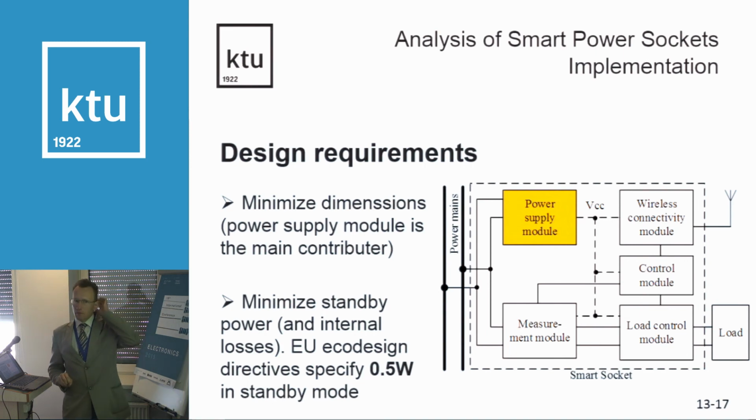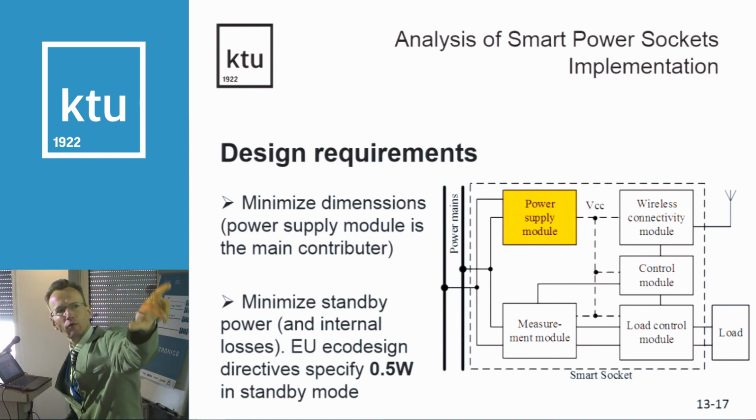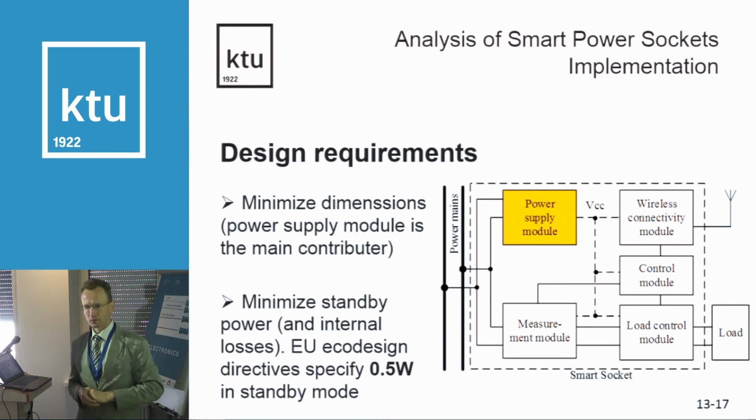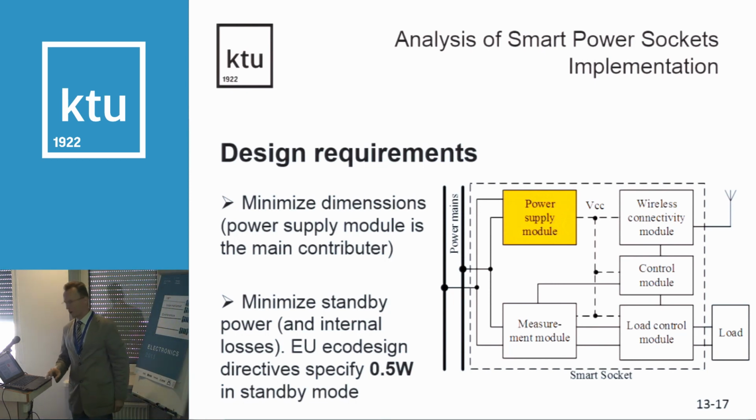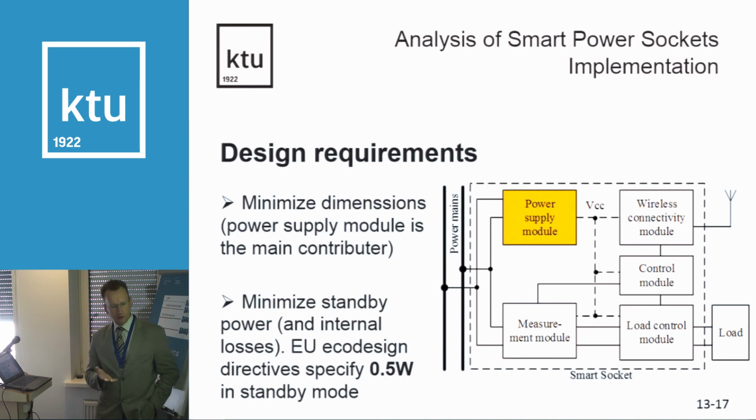Then I will finalize with the measurement errors. Several slides about the power supply module, which is responsible for the energy efficiency of the power socket itself. We were keen to find out if, using many off-the-shelf components, we can at least achieve the EU eco-design directives, which ask for less than 0.45 watts in standby mode of any consumer or mass production device.